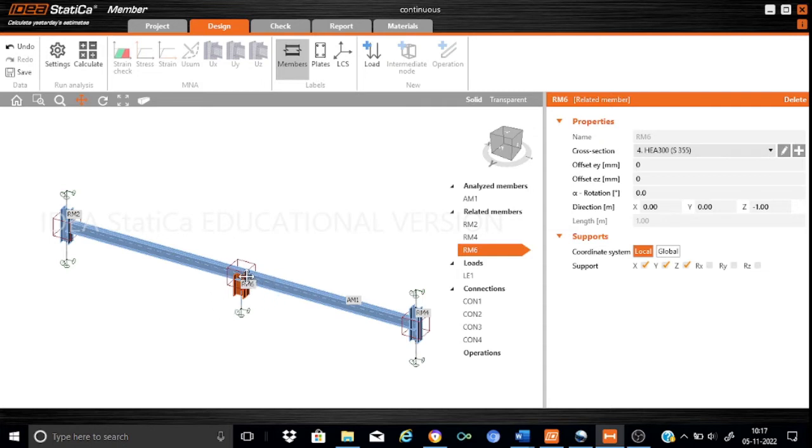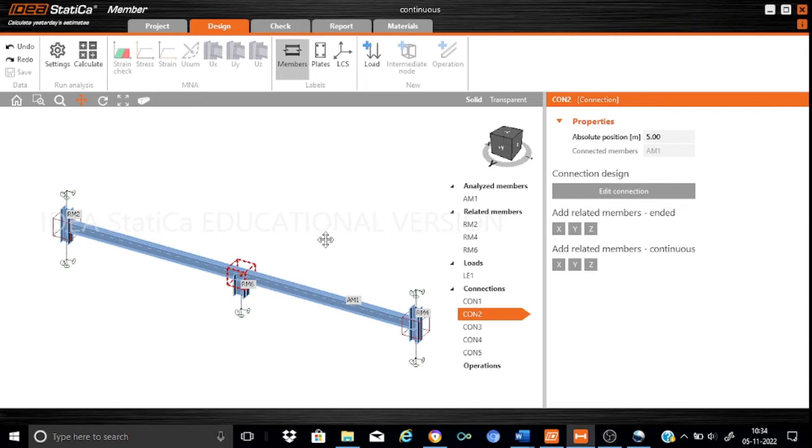Now we want to create a beam in the y direction, and this beam which we are going to create will provide a restraint. This beam is going to critically affect the analysis of this continuous beam against the lateral torsional buckling, or it will critically influence the linear buckling analysis that is being carried out. Okay, fine. So now we need to generate a member that will introduce the restraint to the buckling at the intermediate support.